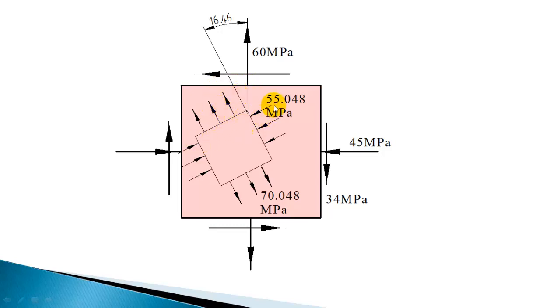On this other principal plane the tensile stress is acting. Along with this, there will not be any shear stress on these planes. On principal planes you have no shear stress. So that is the importance of principal planes. Now you have shown the principal stresses on a properly oriented element.